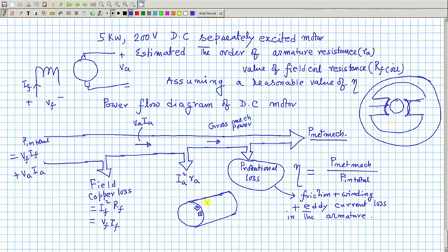Therefore, in the iron body you pick any closed path, it will sometimes see maximum flux linked by this assumed closed path, sometimes zero flux. There will therefore be an induced voltage by Faraday's law, an AC voltage; there is no commutator and rectifier here. So there will be eddy current paths available on the body of the iron, and the iron will also become hot.